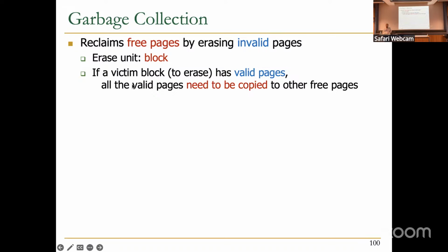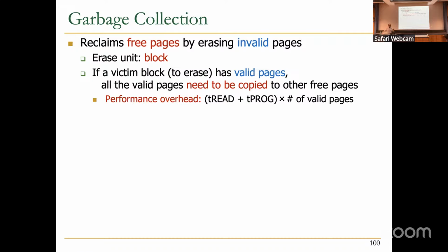If a victim block that we want to erase has valid pages, all valid pages need to be copied to other free pages. And then there is a performance overhead here. Actually, it's the most important performance overhead of garbage collection, where you need to copy valid pages from one block to another block. That also comes with a lifetime overhead, because you now have additional writes, which increases program erase cycles.